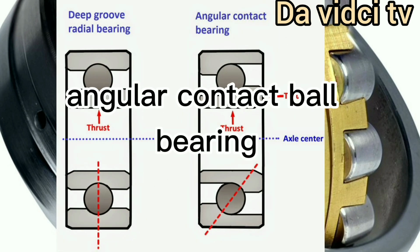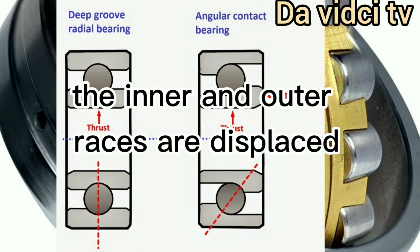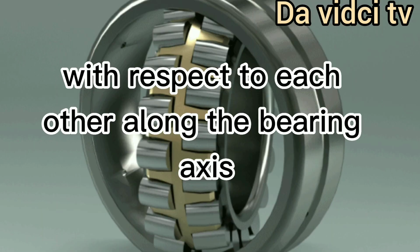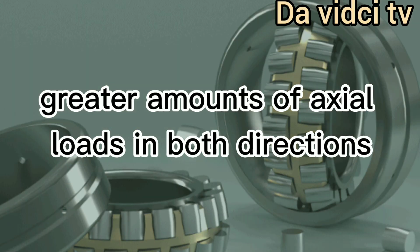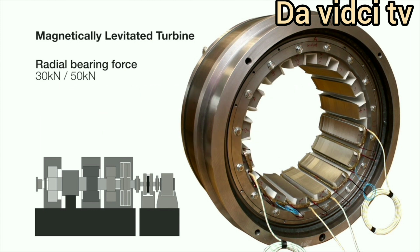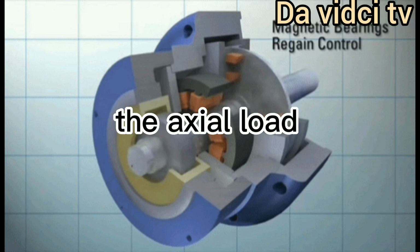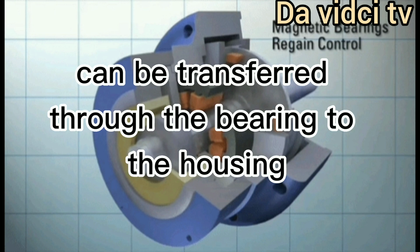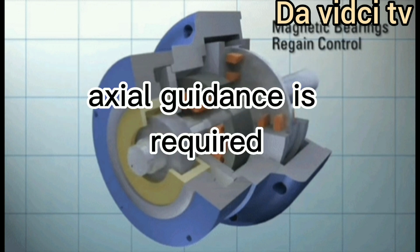Angular contact ball bearing. In this ball bearing type, the inner and outer races are displaced with respect to each other along the bearing axis. This type is designed to handle greater amounts of axial loads in both directions in addition to radial loads. Due to the shift in the inner and outer races, the axial load can be transferred through the bearing to the housing. This bearing is suitable for applications where rigid axial guidance is required.